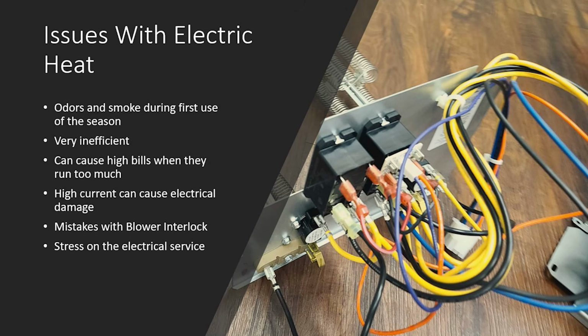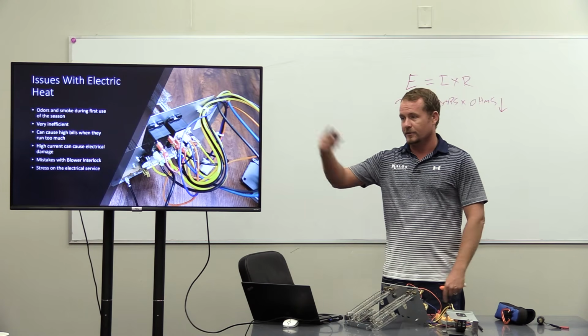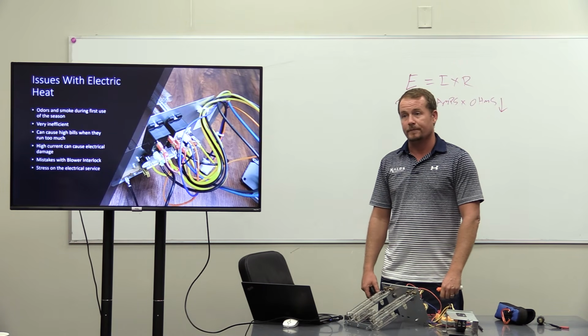And then stress on the electrical service. This is another one. So when we go from a gas furnace to a heat pump with heat strips, can we just count on the fact that we can just swap that? Just, hey, you got a gas furnace, we're just going to put a heat pump in with heat strips. No, we can't count on that.